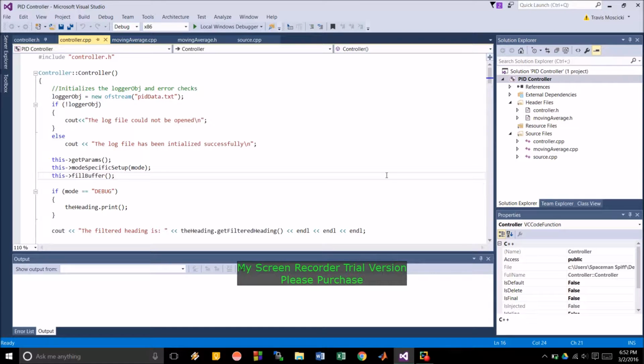Now, for my money, I'm going to turn it on when I get within that plus or minus 3%, because the whole purpose of the integral term is that your steady state error goes to 0. So if you're turning it off once you get within that steady range, then what's the point of having it in the first place? So the anti-windup feature, you want to turn it on once you get within a certain range of your set value.